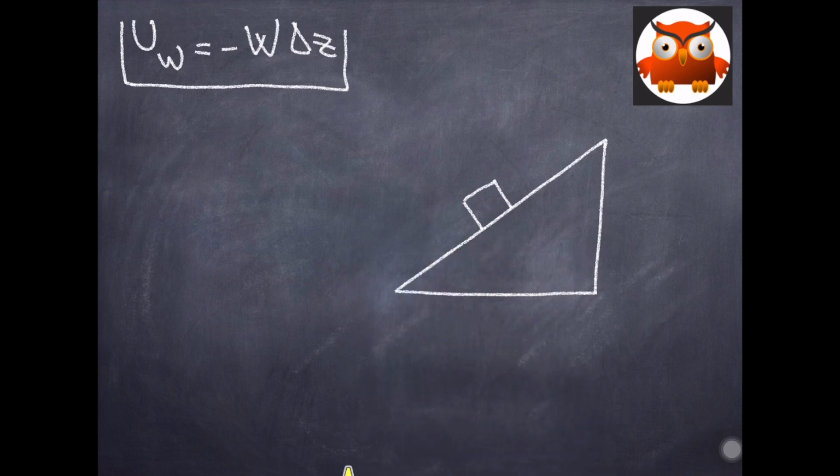So I ask them to calculate the work done by the weight using mg times the height, being the vertical distance between position 1 and position 2 under consideration. Then they can put positive or negative in front of the expression based on whether the weight is doing positive work or negative work. Whether the weight is doing positive or negative work all depends on the dynamics of the system itself.